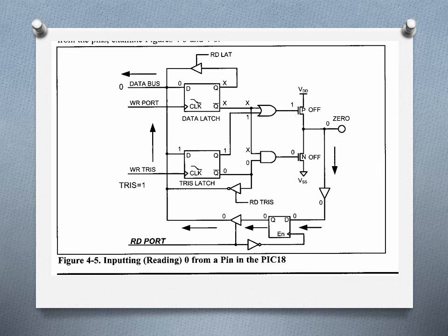What one should understand is that the whole circuit should be cut off and the value from the output should come through the bottom D flip-flop. So you can see here the tri-state is 1. So when it becomes 1, you can see the 0 value to the AND gate and 1 to the OR gate. So what will happen, even if one input is 0 to the AND gate, the output is going to be 0. And if one input is 1 to the OR gate, the output is going to be 1. So both the transistors, the PMOS transistor and the NMOS transistor, are off. So as these two are off, the whole circuit gets into a high impedance state, that is, you don't have any values to send to the output. So this will be acting as an open drain.